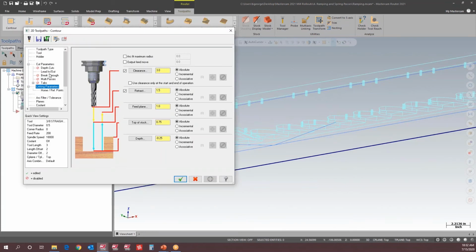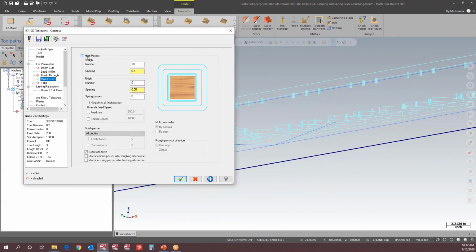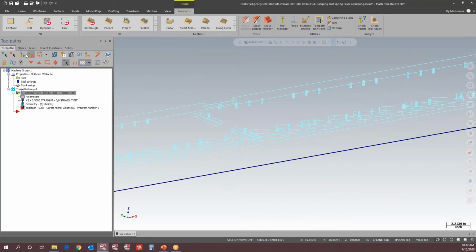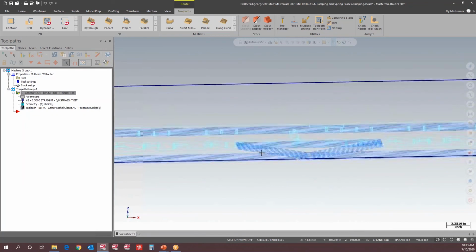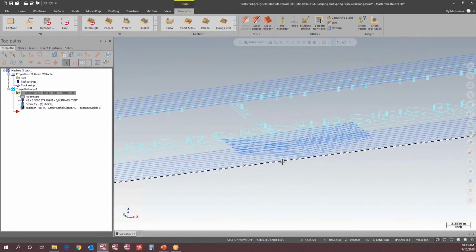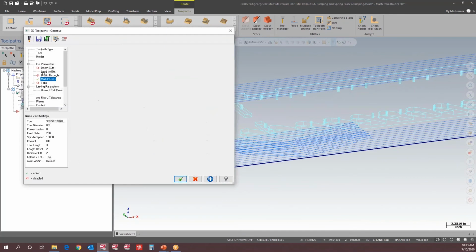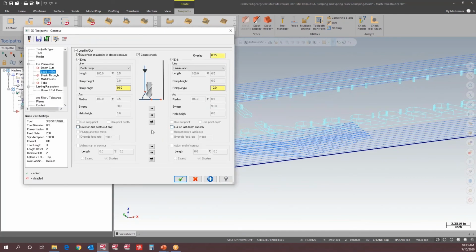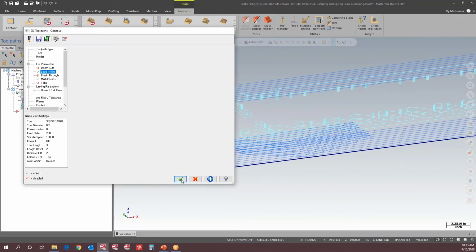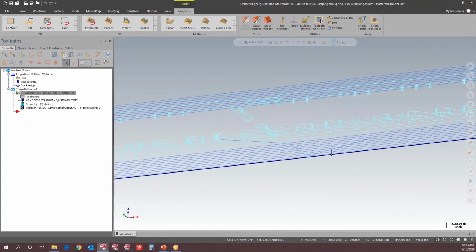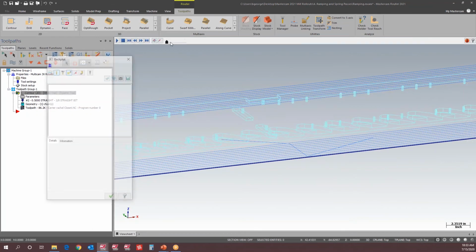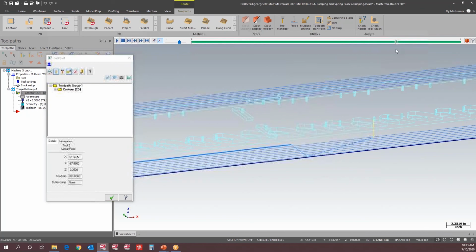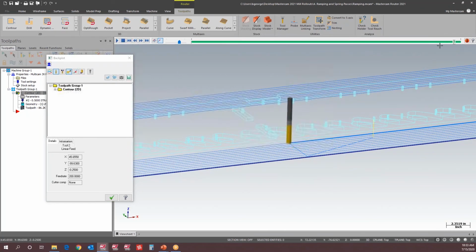And this is also going to go in line with multipass. So if I turn on multipass, you'll see every single time I do a multipass, it's going to do my lead in, lead out at that 10 degrees, but it's also going to respect the start and end only one time. So I only want it to ramp in at my entry and my exit. And what we'll see here is that nice one ramp in, and then the tool is going to stay all the way engaged for its 10 cuts and then ramp out. So again, it's a small improvement, but it's a thing that people have definitely been asking for a little while now.